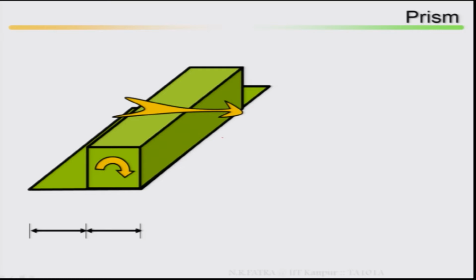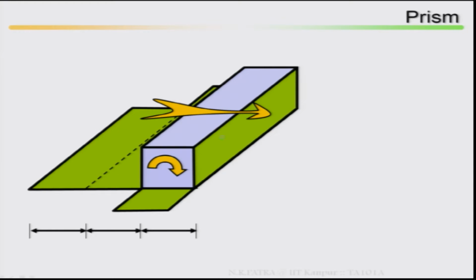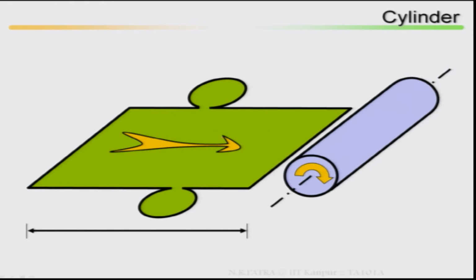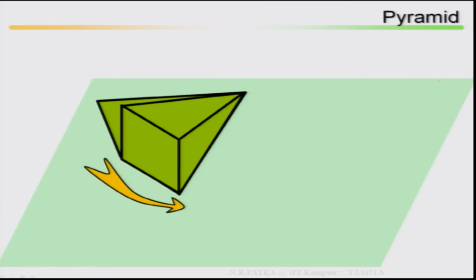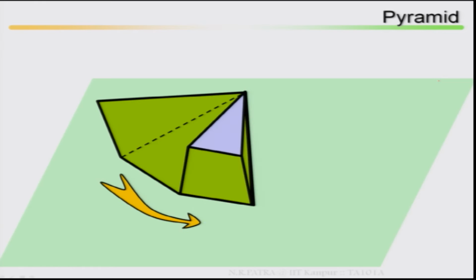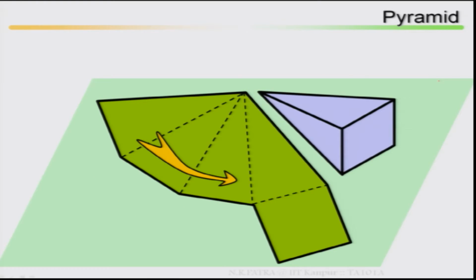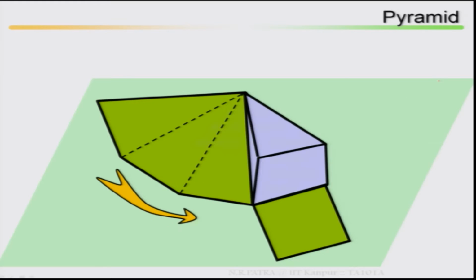Then look at here, the prism has been folded or developed, the surface has been opened up. How has this been opened up? This is your developed surface of the prism. Similarly, cylinder, this is the developed surface of the cylinder. These are at the top, this is at the bottom, it has to be packed from both the ends. Then pyramid, look at here, opened up, rolled around,